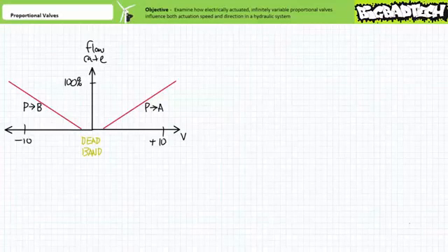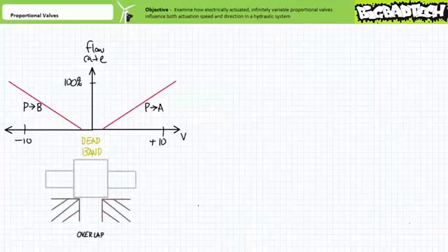Deadband is a byproduct of several non-negotiable realities. One being spool overlap, where overlap means the spool land must be slightly wider than the passage it is intended to block to ensure positive seal. Another being friction of the spool against the valve body and oil impurities, and another being magnetic effects we'll examine in a moment. The flat zone characterizing the deadband means a certain minimum amount of voltage must be applied to the proportional valve for it to open at all.